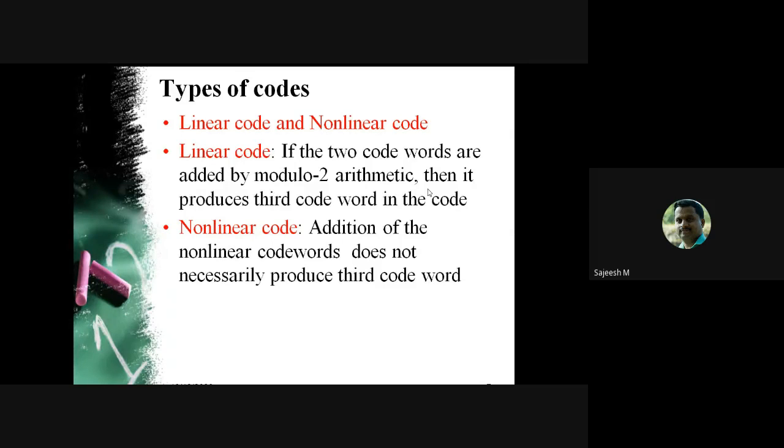If we take any 2 code words and add them by modulo 2 arithmetic, the output of that addition will be another code word in that set.